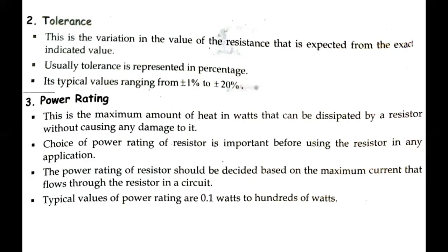Okay, choice of power rating of resistor is important before using the resistor in any application. The power rating of the resistor should be decided based on the maximum current that flows through the resistor in the circuit. Typical values of power ratings are 0.1 watts to hundreds of watts.